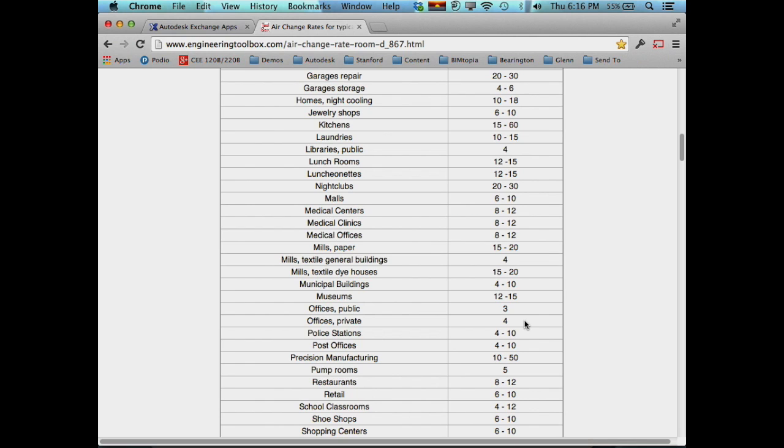Okay? And as we go through and do that, we go a little bit further. In terms of your in and your out, very often we'll figure out where it's going to do the most good to introduce the conditioned air, the air that's the temperature we want, versus taking away the air which is stale or has lost some of its power. Here's how it often works. We will often put the intake basically near the windows.